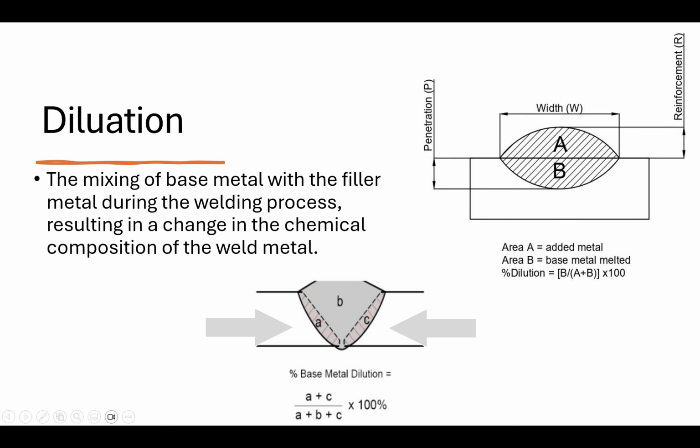the electrodes. In the melting, the surface is going to melt. So imagine the area C and A both will melt during the weld. Now, say this side is A106 grade B, a carbon steel side. So this is the carbon steel side, this is the stainless steel side. And this is pure electrode deposit.